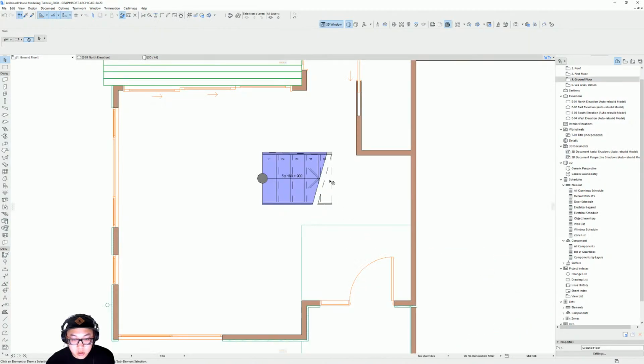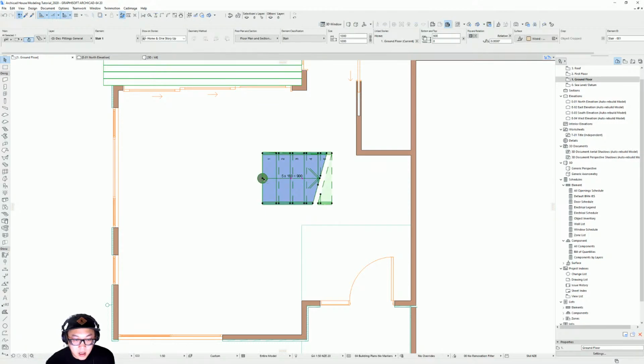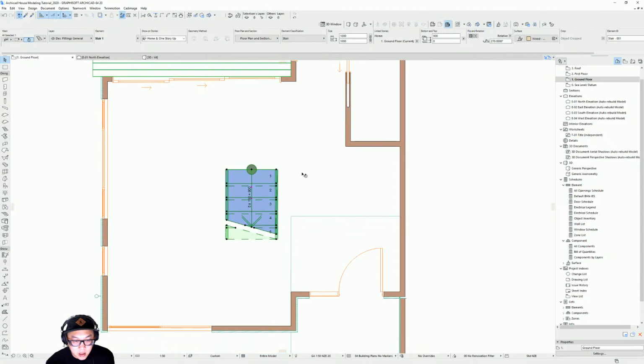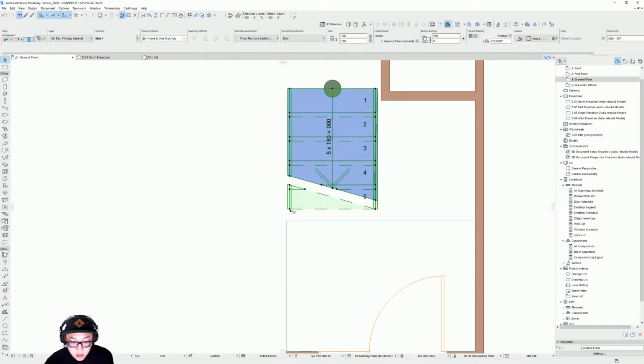Press F2 and select that, and if you click once on any of the black nodes here, you get that little window that pops up, and you go to rotate, you click once and that's the reference line, and then from here you can choose your angle and make sure it's 90 degrees so it's square, and then you can press Ctrl D to drag the element and put it into place.